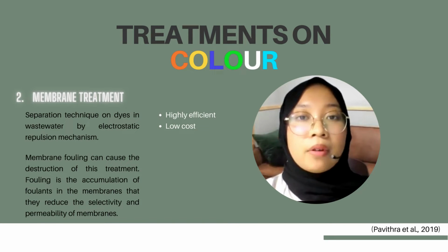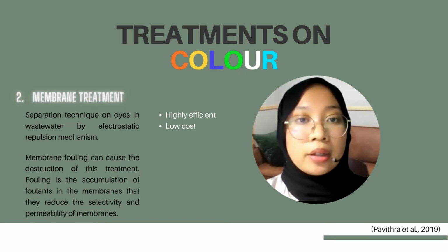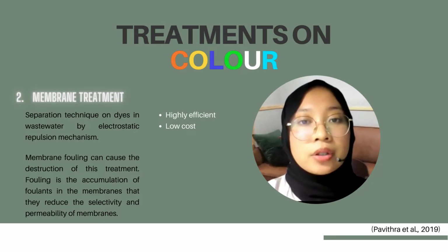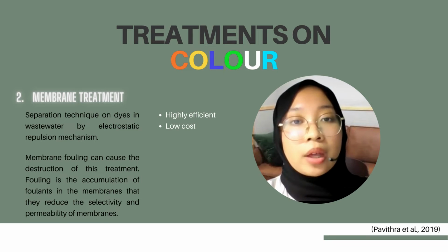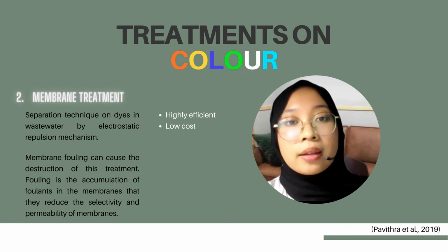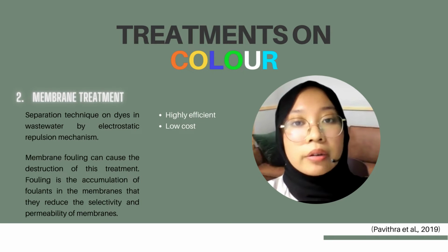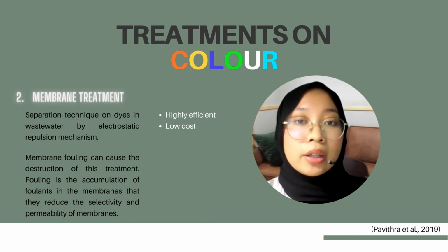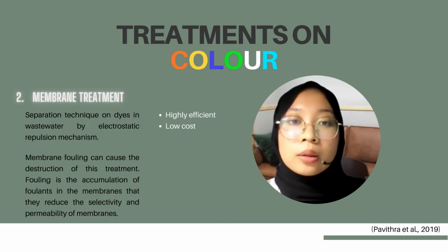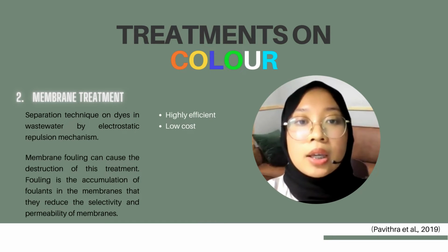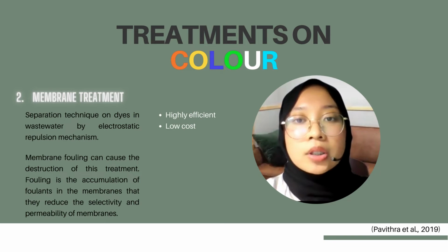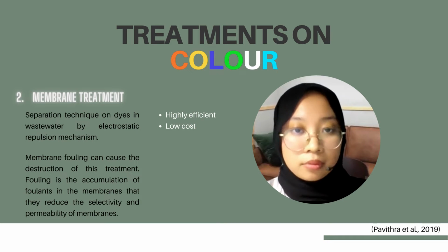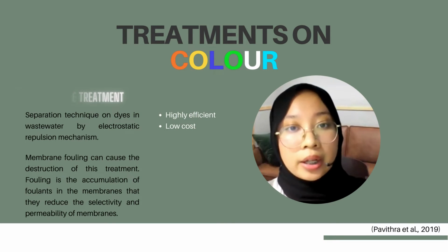The mechanism involved is separation technique by electrostatic repulsion. So this technique is highly efficient and low in cost in comparison with other advanced treatment. There are many techniques of membrane treatment that are recently introduced, such as nanotechnology. However, the disadvantage of this treatment was reported in terms of the accumulation of foulants in the membrane, that it reduces the efficiency of the membrane to select and permeate the materials such as color and dyes.